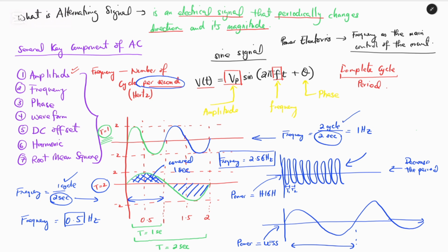When you talk about the buck converter and the boost converter, the control is the duty cycle, and the duty cycle represents the on and the off switch. And the switch is nothing but the MOSFET, which is used to control the duty cycle to the particular MOSFET. And this duty cycle has the frequency.